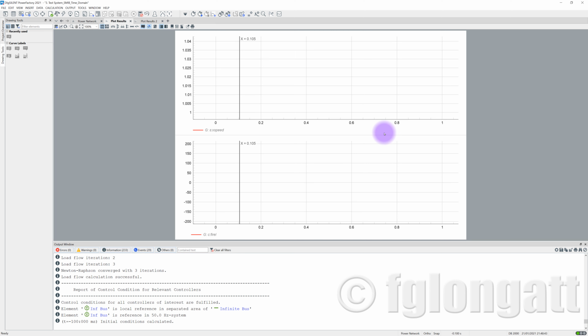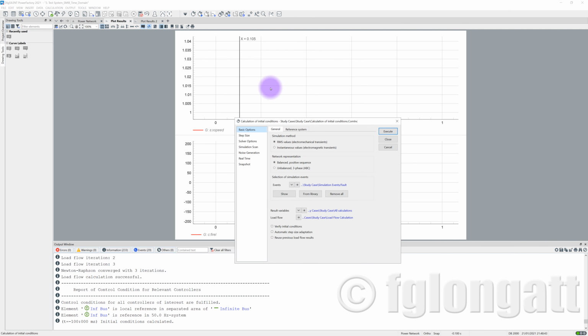There is a maximum moment that we can support the fault inside the power system before the system loses stability. I will repeat again. There is a time such that if we clear the fault before it, the system is stable, and if we clear the fault after that, the system is unstable. That very specific moment receives the name critical clearing time, okay? This is the name: critical clearing time. What I will try to do here, in just a few simulations, is define that moment, okay?